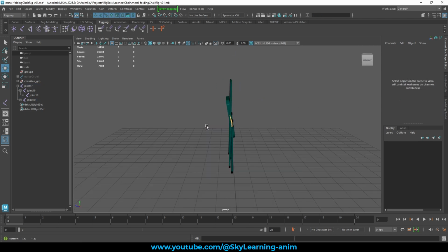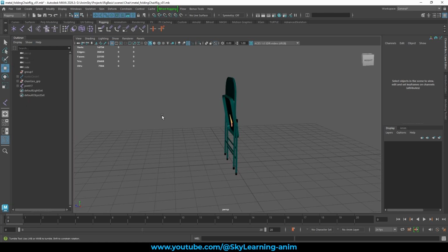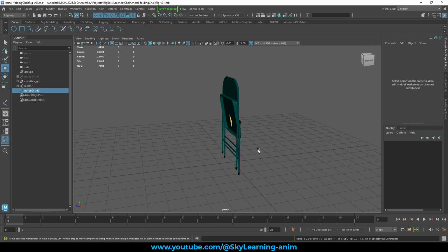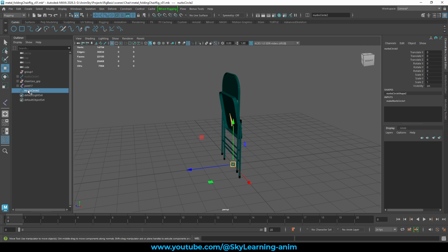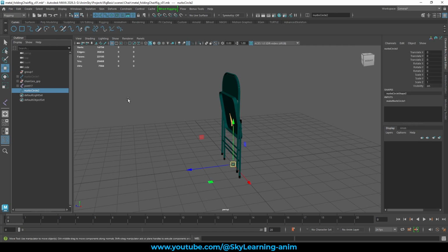So let's keep this in pose, and why not start with a custom control. As I promised you in the beginning, we need one more control for that. So we can use a control attribute, custom attribute. We can change the value either 1 to 10, and this folding animation should happen. We don't need to go to each and every joint and rotate it and animate it. So yeah, so make it